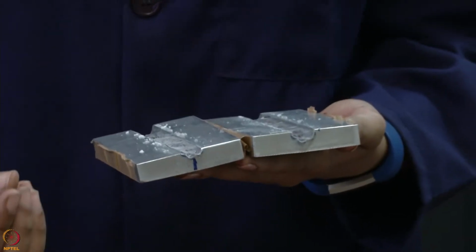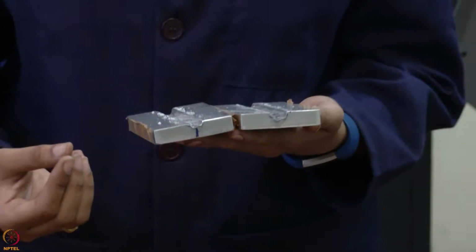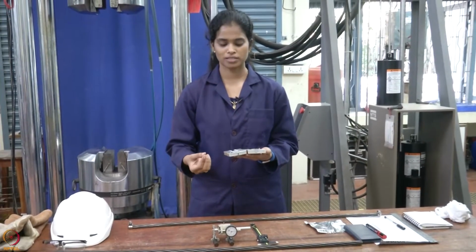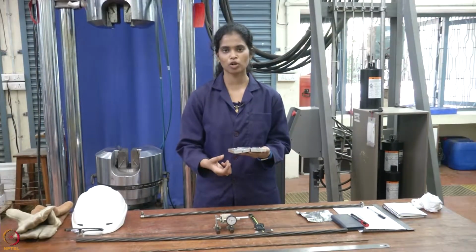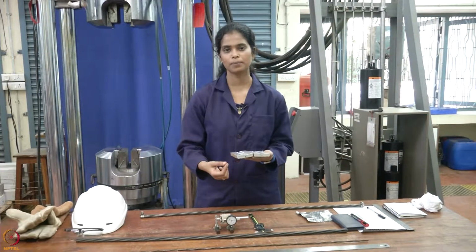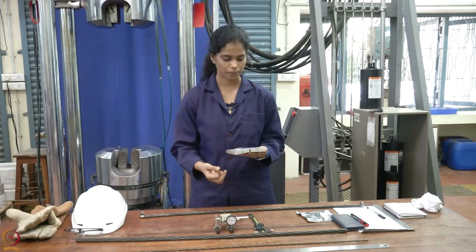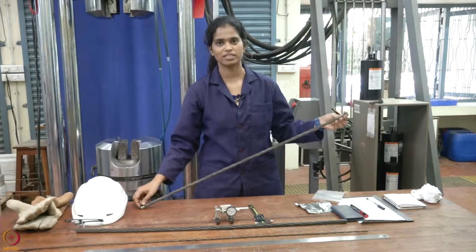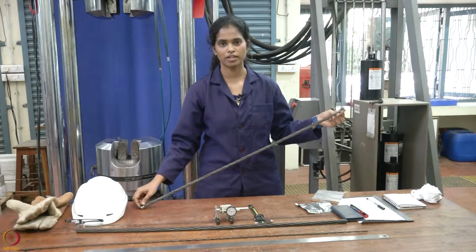During testing we may face some slipping, so to avoid that, the ASTM specification suggests using an aluminum oxide slurry made using glycerin. We have placed clamps at both ends to make sure that the strand is not slipping or rotating during the testing.